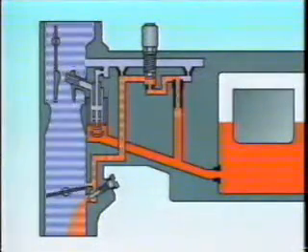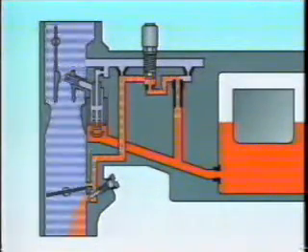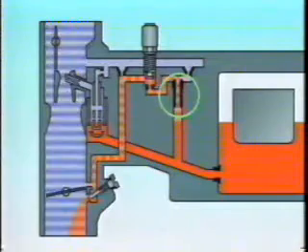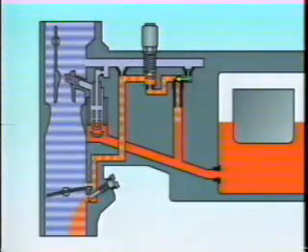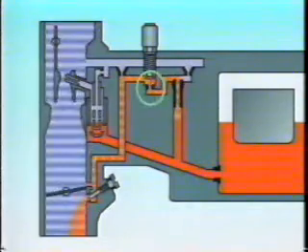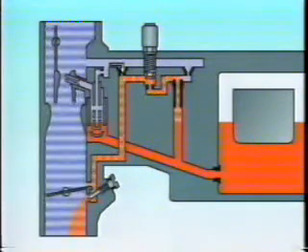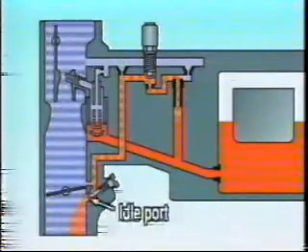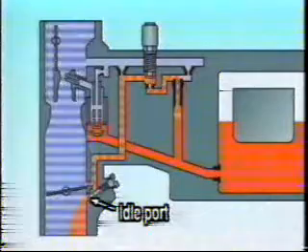The actual flow of the fuel is as follows. It leaves the float chamber and passes through the main jet, then through the slow jet, which controls its volume. It then goes to the primary air bleeder, where it is mixed with air, and then to the economizer jet, where the volume is further controlled. Then the air from the primary air bleeder is mixed well with the fuel and delivered from the idle port.